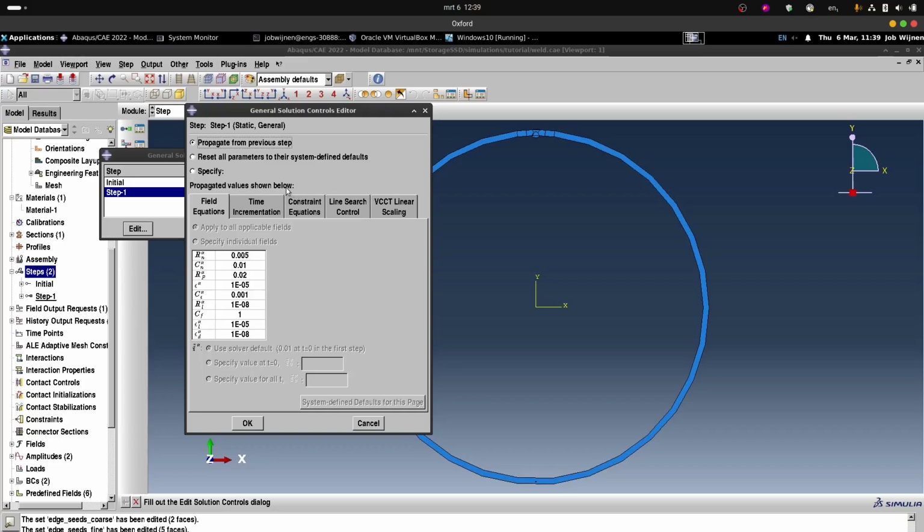Basically, in a fracture simulation, in increments where crack propagation occurs, convergence usually takes place after a few hundred iterations. And Abaqus, already way before that, thinks your solution is not converging and aborts the increment and cuts the time step. So we want to avoid that.